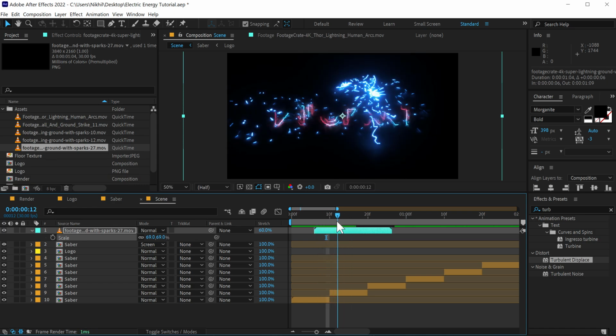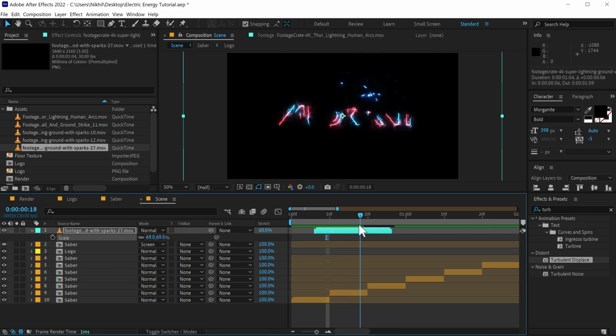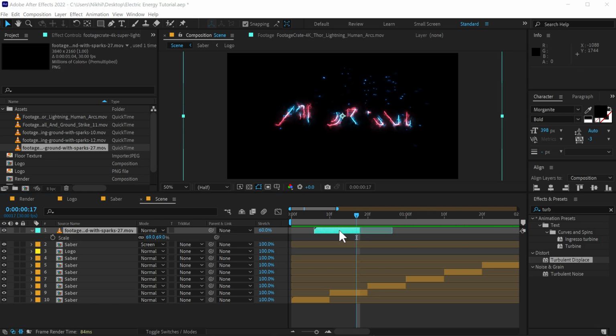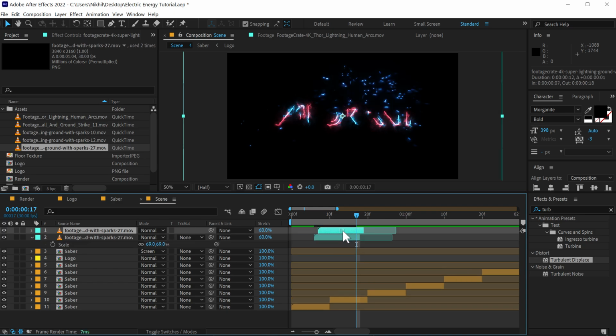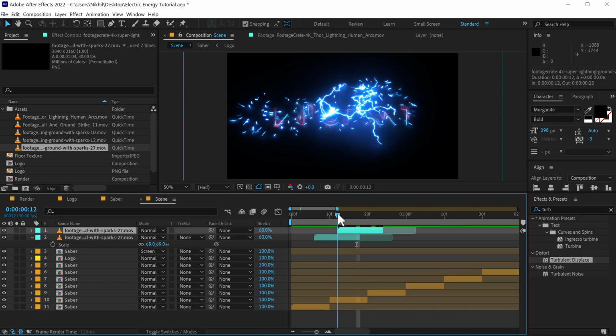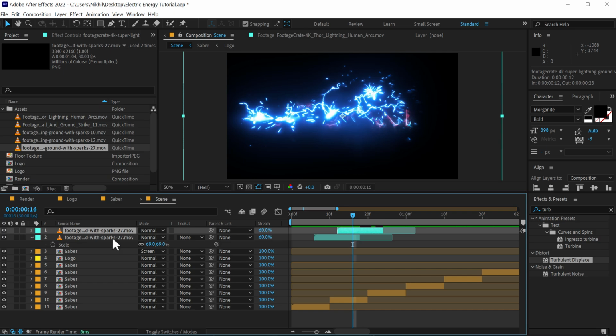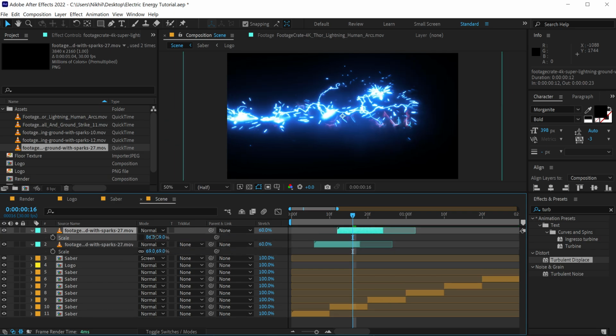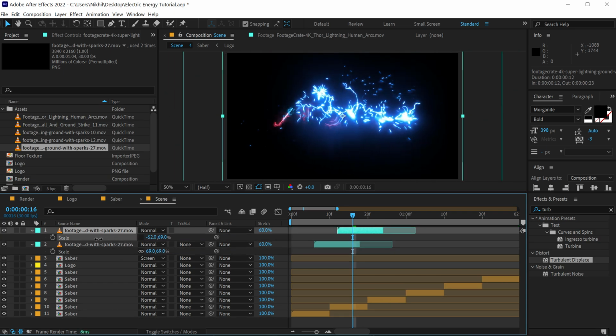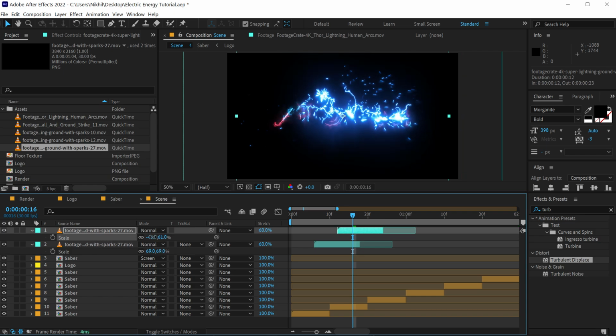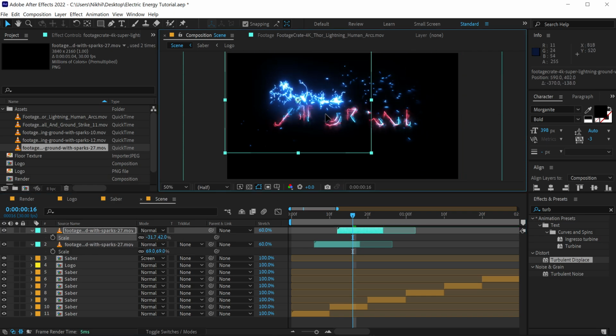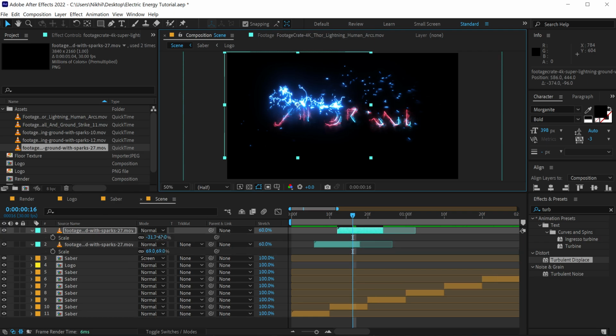It also works as a transition, as you can see, from the first scene to the second scene, which is really cool, by the way. And then I'll just crop this, so hold Alt and right square bracket. There we go. Then I'll duplicate this, press Ctrl D, move this a bit forward in time like so. And scale this. So I'll unlink this, scale this like that, just to add a bit more randomness, and then scale that down. Maybe add one right here and rotate it a little bit like so.